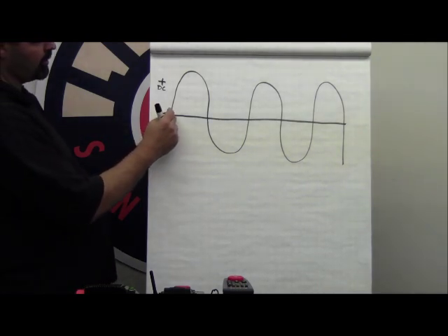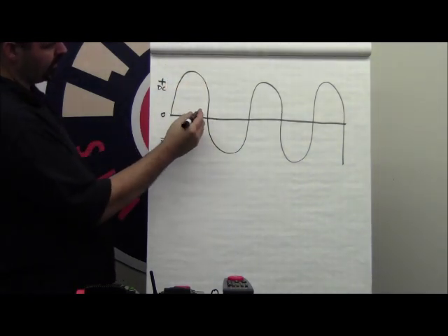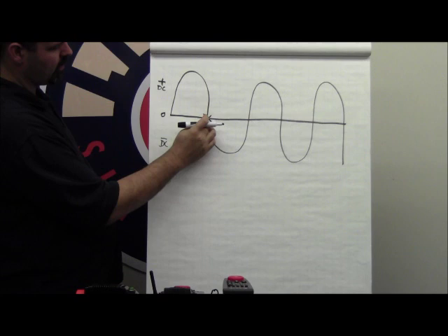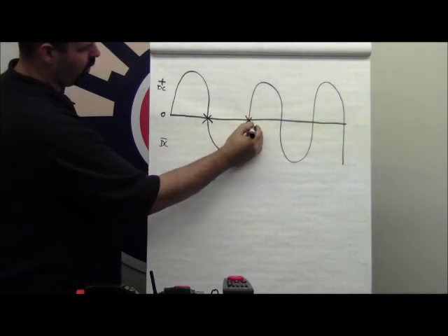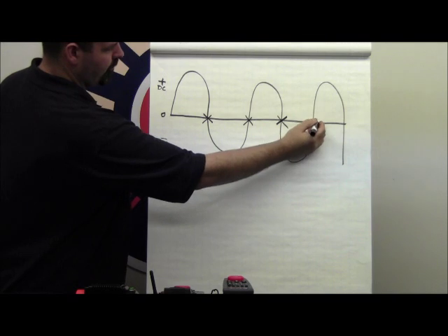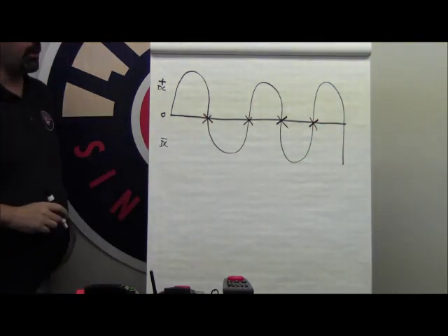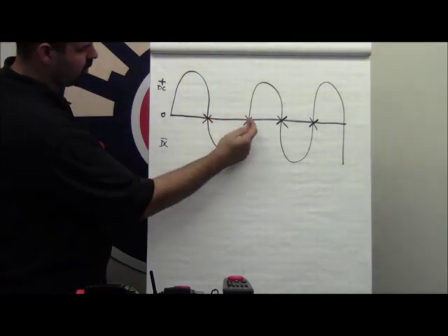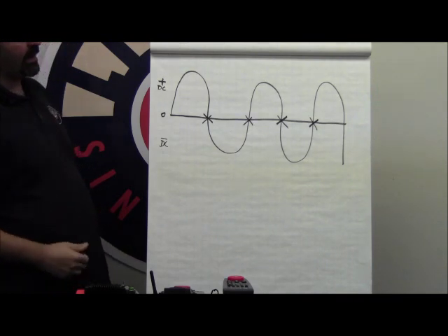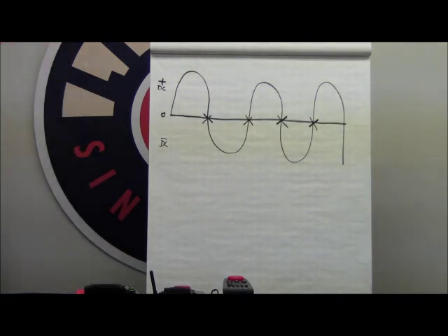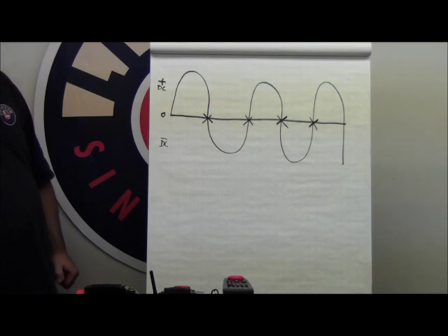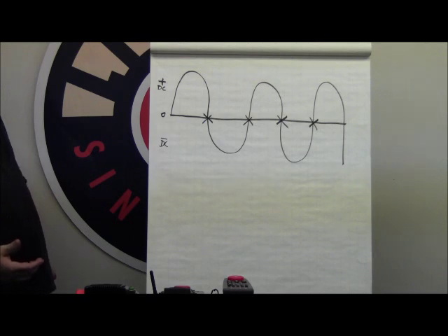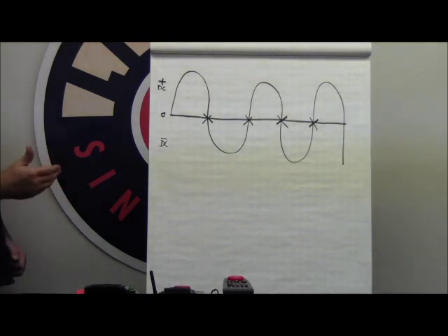What's important to note about this sine wave is that every time the voltage crosses the zero line, it creates what we call a sync pulse. This sync pulse occurs 60 times a second. At each sync pulse, a burst of signal is sent out of the command base through the halo that is transmitting out of both outside rails on the track and being received by the antenna inside your locomotive.